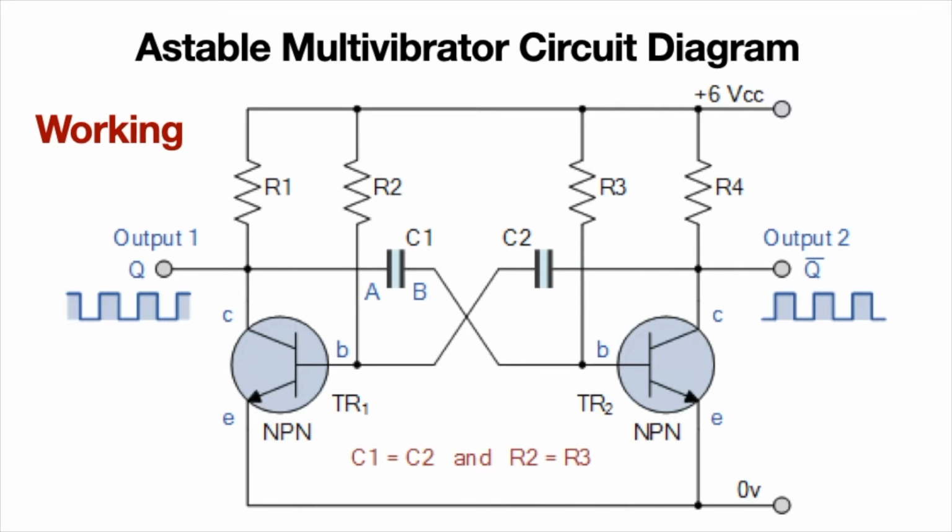And when the voltage is applied, at that time the capacitors will start charging. We know that it simultaneously starts charging, but how they start charging, that we need to understand. In our circuit we have designed it in such a way that the value of collector resistors is less than the base resistor, right? And therefore in the circuit the capacitors will charge through the collector resistors and not through the base resistors.